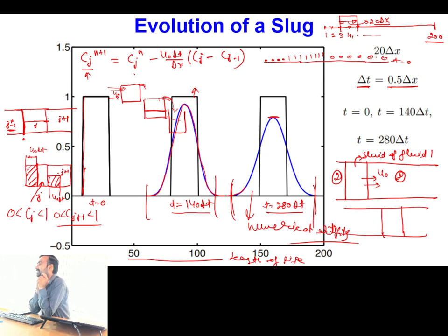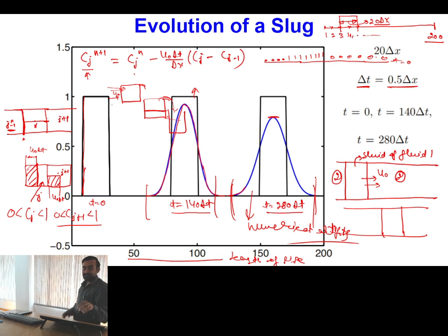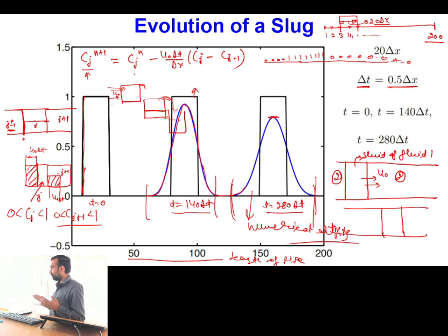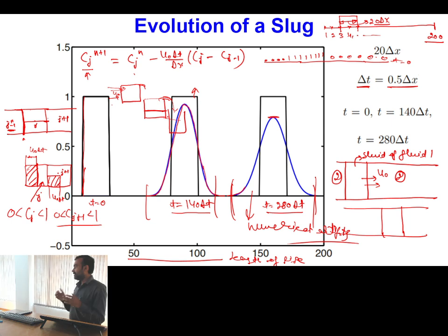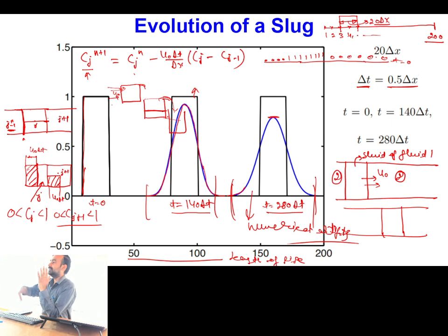If the number of these cells increases, my interface shape will be distorted, because for defining a proper interface, a minimum number of cells should have volume fraction between 0 and 1. In this way, the partial value of the color function spreads over a larger portion of the domain.